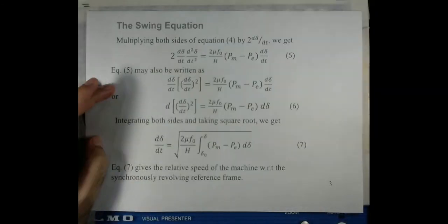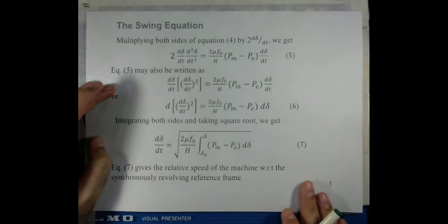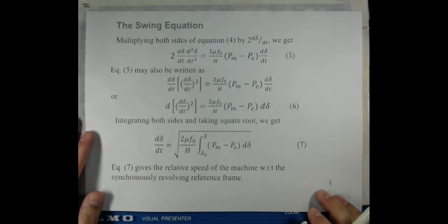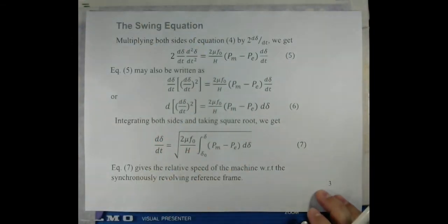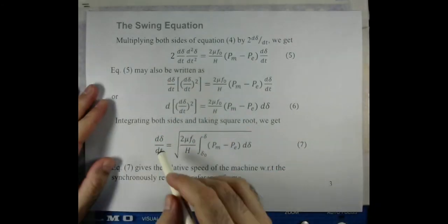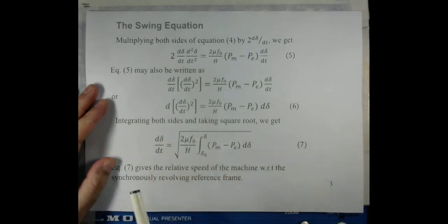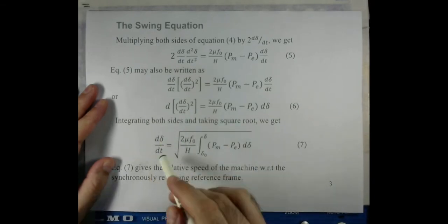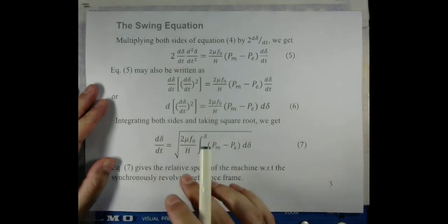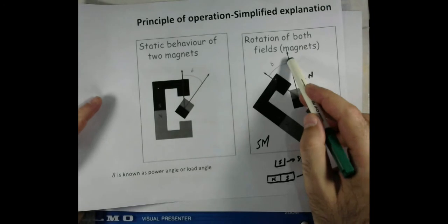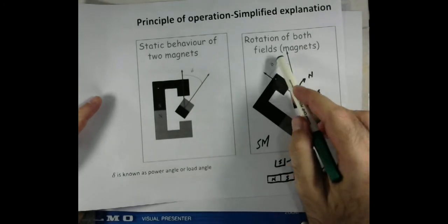So as we are discussing transient stability, which accounts for large disturbances that could appear in the system, if after a disturbance we analyze the system, there will be change in the angle, and that will give us the relative speed. Because if the change in this angle is 0, it means that this angle obviously will remain the same.